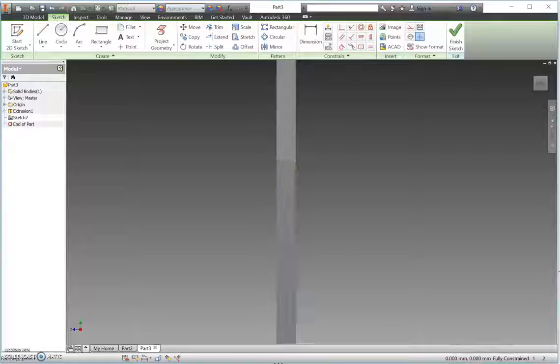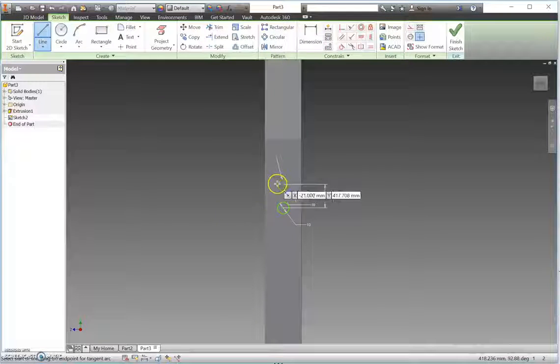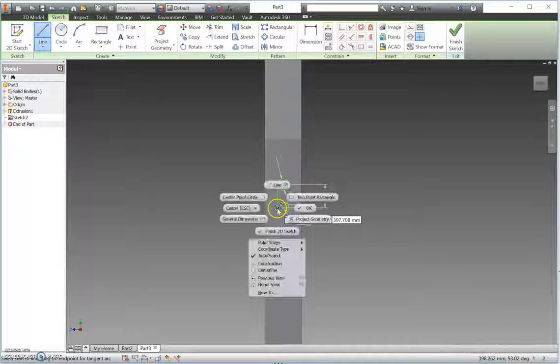Okay, so I'm just going to start by drawing a circle from this little green point. That gives us a centre. So type in 10, enter. I'm going to draw another one, making sure you've got that dotted line, so you're not having to over-constrain things. Okay, from the midpoint, we're going to have 20 millimeters. And I'm just going to link these up.